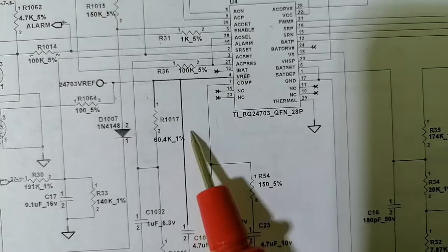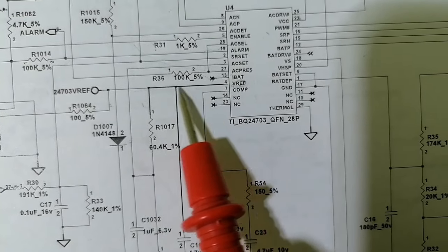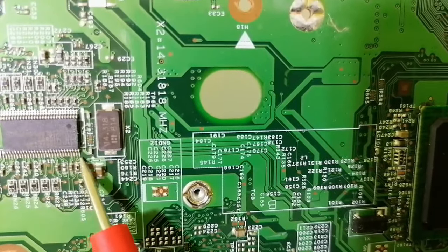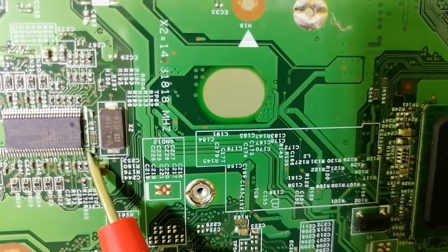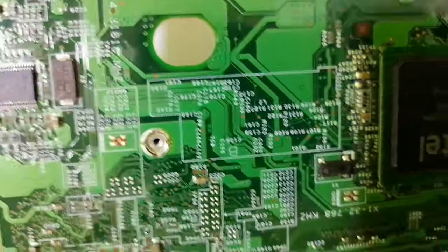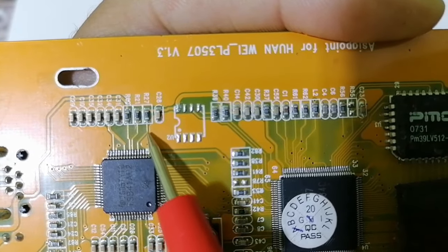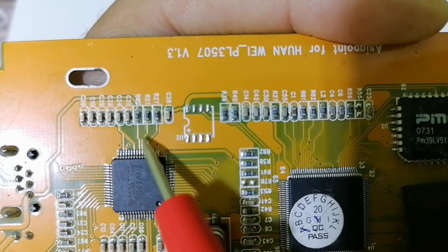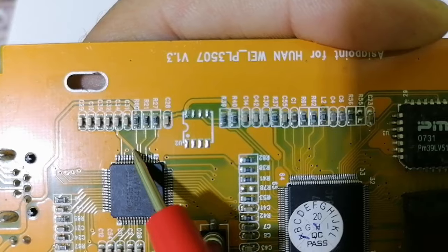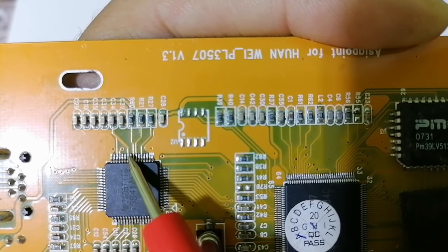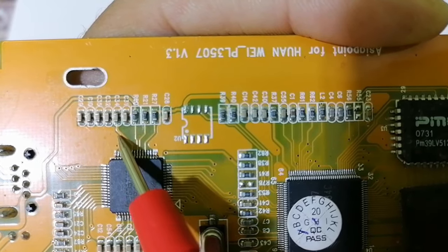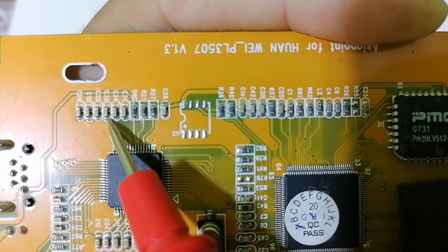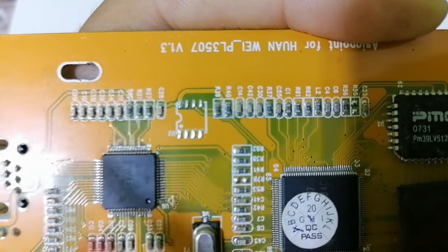And for the voltage, we have this bolded line, exactly as the IC. The thin lines are control signals, and the bolded line means the power for the IC, exactly as we have in the motherboard, as you can see. So these thin lines are just enable signals, and the bolded line here is for power. So here, for example, let's assume that the power here is 5 volt. If you don't find 5 volt here, you should go and check this capacitor. Is it good or not?